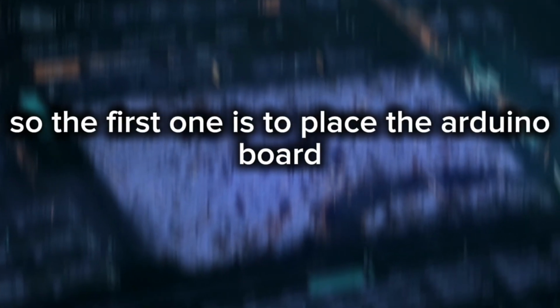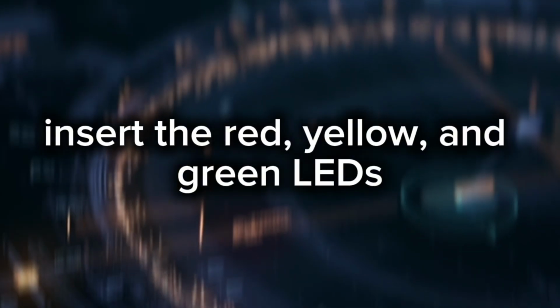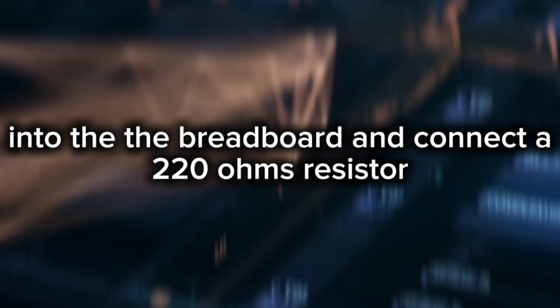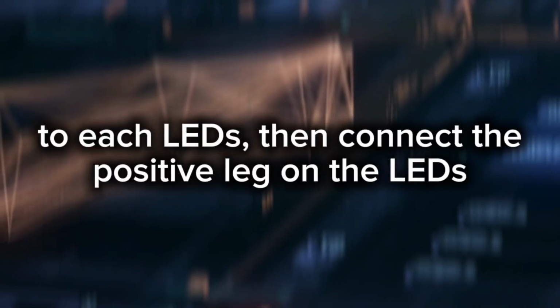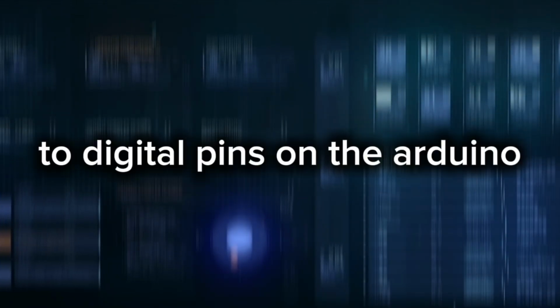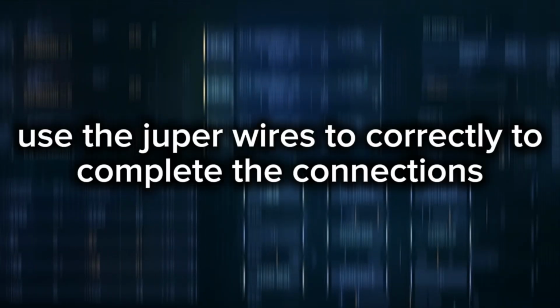So our procedure is setting up the circuit. The first one is to place the Arduino board and breadboard on a flat surface. Insert the red, yellow, and green LEDs into the breadboard and connect a 220 ohm resistor to each LED. Then connect the positive legs of the LEDs to digital pins on the Arduino. Then use the jumper wires to complete the connections.